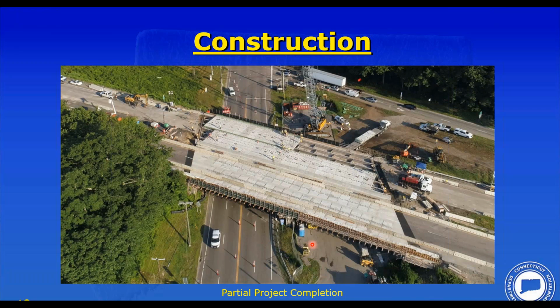In this case, it wasn't the case on this bridge because as Tim mentioned, the steel wasn't in that bad of shape. But a lot of times we're finding that with modular deck beams, it's actually less expensive, and a lot faster to build because you're not making that deck connection to the beams. The unit comes from the fabrication shop already composite, and all you're doing is connecting a deck level connection, which is quite simple. So we're seeing that type of construction becoming much more popular in the Northeast.